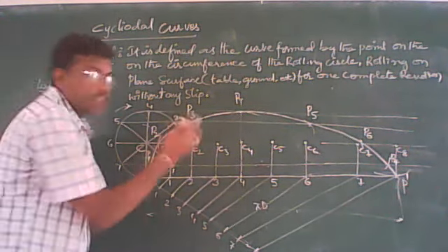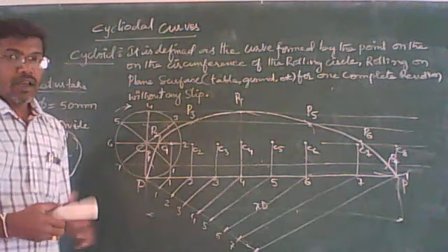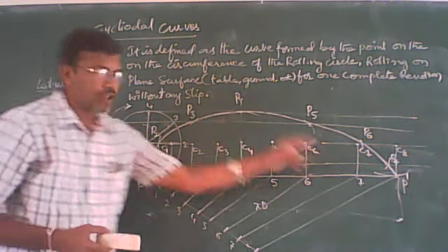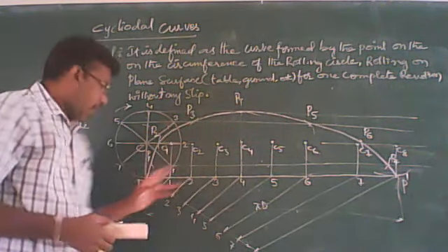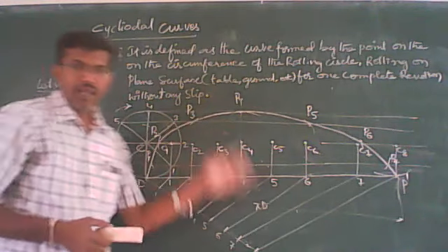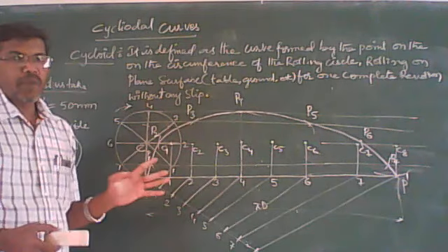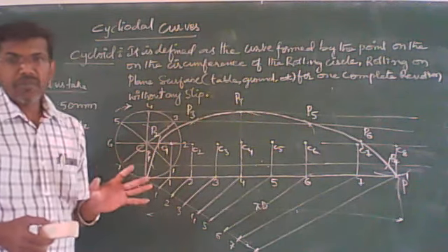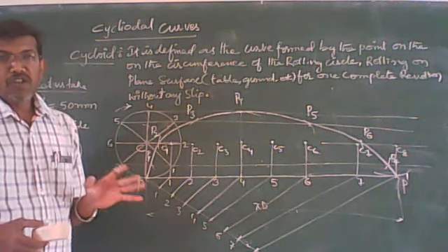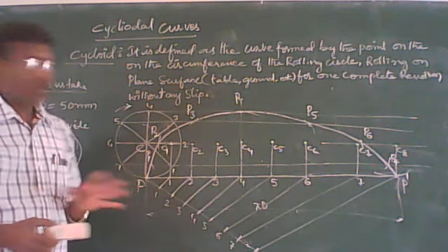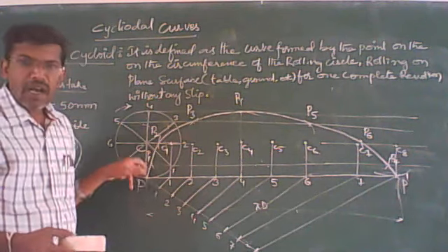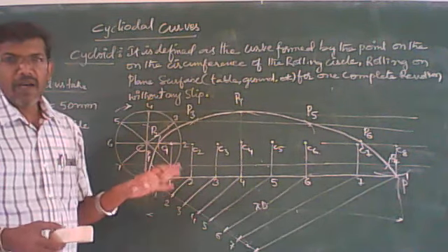So now this should be done. So you can see the picture. Only the cycloidal curve and PP dash should be dark. Other than that, all the lines should be thin because all the lines are the construction method, so the lines should be very thin and light. Only the circle and the PP dash line and the cycloidal curve should be thick and dark.